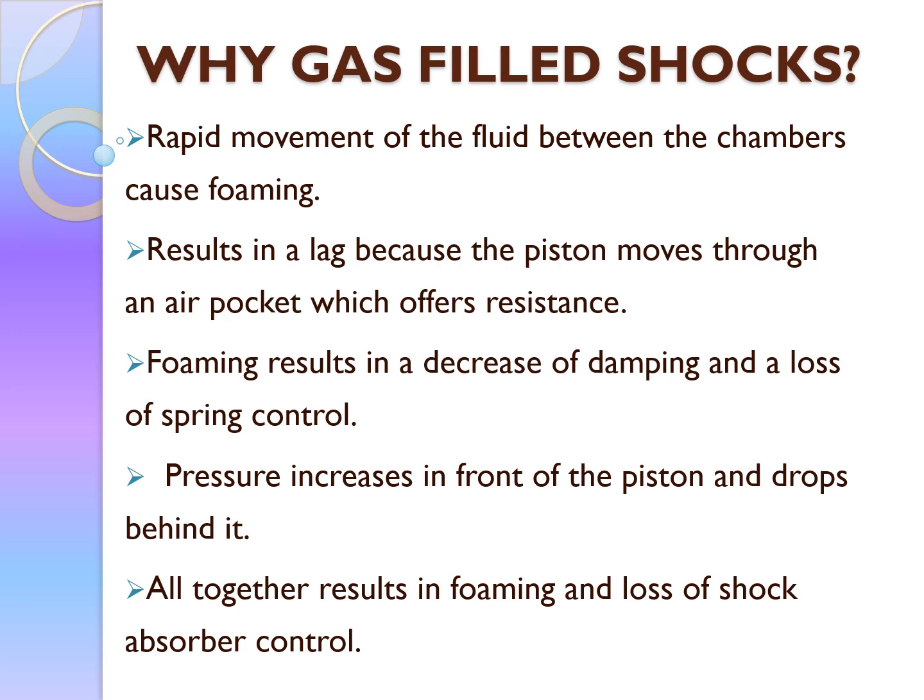And why do we need gas-filled shock absorbers? The rapid movement of the fluid between the chambers causes foaming and results in a lag because the piston moves through an air pocket, which offers resistance. Third, foaming results in a decrease of damping and a loss of spring control. Fourth, pressure increases in front of the piston and drops behind it. And fifth, altogether this results in foaming and loss of shock absorber control.